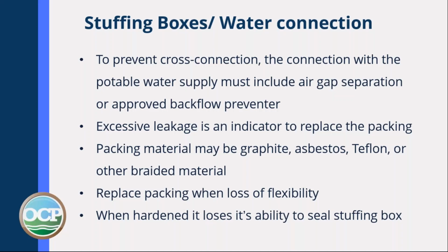Excessive leakage is an indicator the packing needs to be replaced. The packing material may be graphite, asbestos, Teflon, or other braided material. You replace the packing when it loses its flexibility. When hardened, it loses its ability to seal the stuffing box.